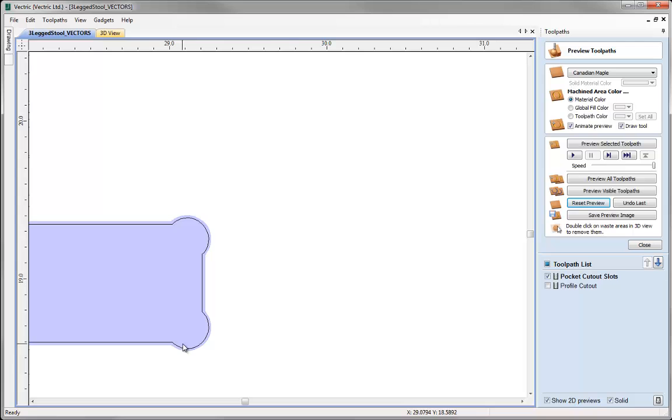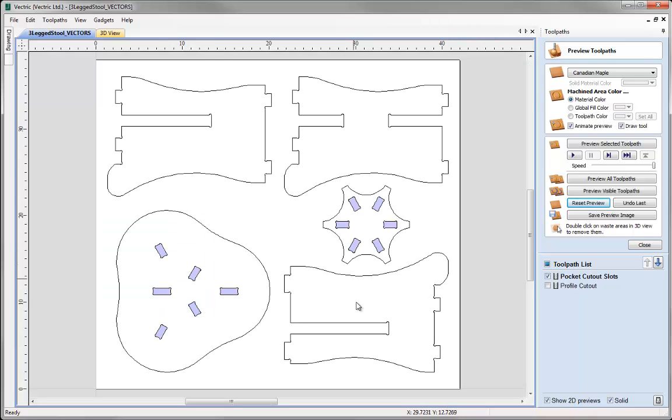They're all going to be slightly overcut, and hopefully that would be enough to allow these parts to slot in. And again, if you wanted to, you could cut a test piece first in order to check to see what kind of value you might need to leave.